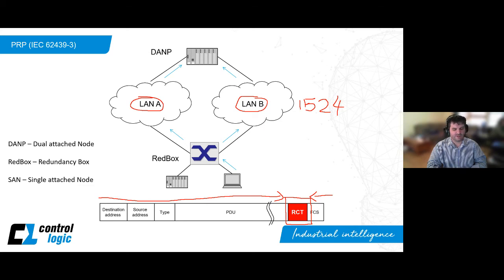Except that most likely in the PLC, unless it's sending data at the same time, it probably is sending it on one card and then sending it on the other if it fails. But if you are coding it to send always on both, then it should be more or less the same outcome. In PRP, however, the duplicates will be removed before sending to the SCADA server. So whilst in your solution you would have both sets of data recorded as being received, in the PRP solution only one copy of the data would ultimately end up at the SCADA system.